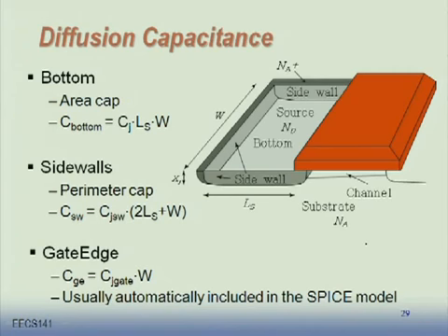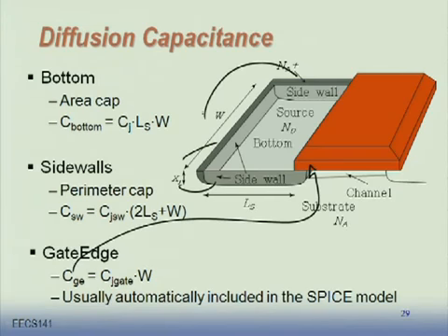But because of a very complex structure, how this drain is being built now, there is some capacitance on that side as well. You have to remember there is something that is called a halo implant, and drain extension and all that forms some capacitive structure down there. In modern devices, this would be correct for most of the drain, and then you'll add one more, a little different value for the fourth side. That's the gate edge. Gate times the W. A fourth value, fourth side of that polygon. So this is what corresponds to this, and these three sides are the rest.